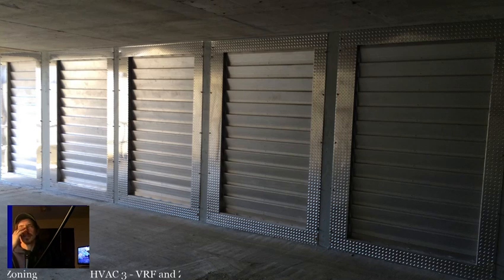So anyway, generally, it's just a solenoid, or it's just a regular valve. It could be a 3-way valve. It depends, man. It really depends on the design. I don't like to generalize things like that. But if you have a 4-pipe system, usually you're just going to have a 2-way valve on the coils. But you could have a 3-way so you can bypass to recirc. It depends. But they say 2-way valve, so I guess remember that. 4-pipe water system, usually the double coils have 2-way valves.